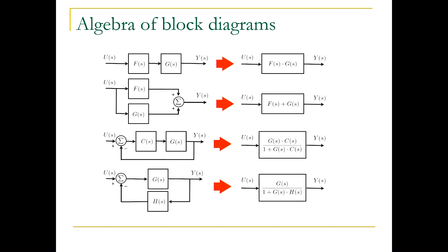But because of this minus, you would find that in the simplified block diagram, you have plus. So if you had plus here, then this would change to minus. I present minus because in feedback systems, we typically use negative feedback, but the formula can easily be changed if you had a different sign here, right? That's very important to pay attention to. You always have to check the signs at the inputs of your summer, right?